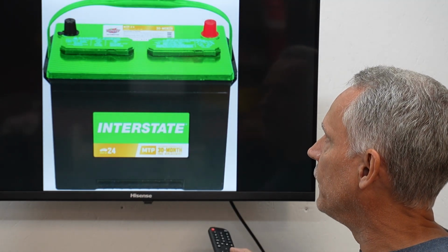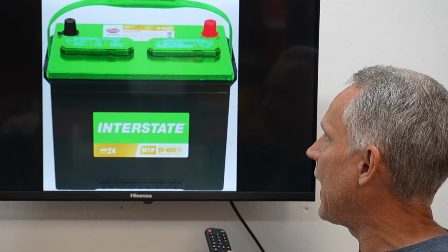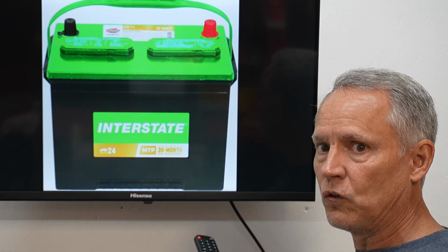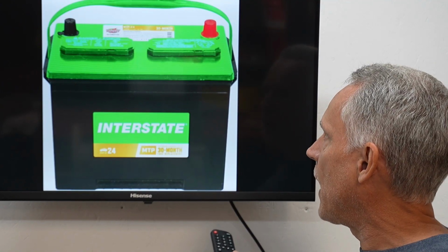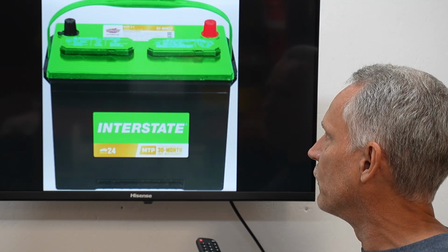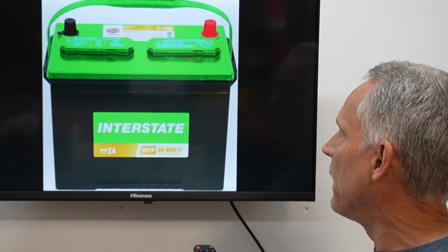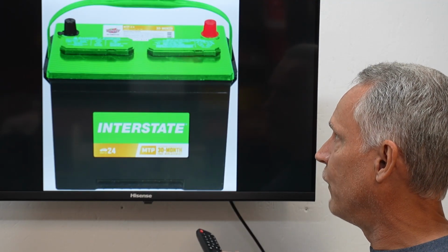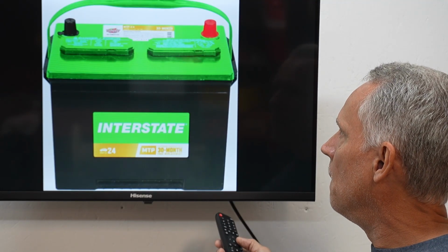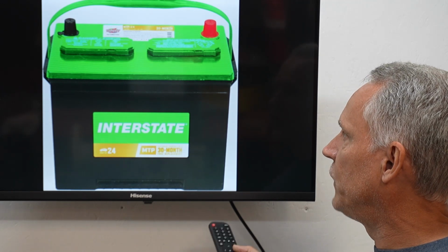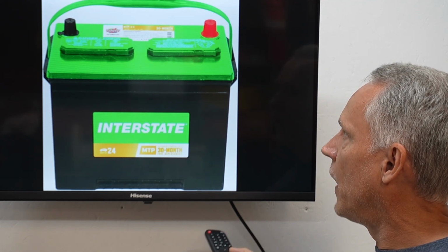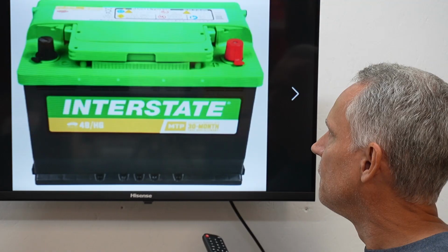Also, a different type of vent system. These caps or vents are exposed. You pop these caps off and you'll be able to see the six ports I'm talking about, three per side, to access the electrolyte down inside the battery. Also, like I said, flooded lead acid, not maintenance free. Standard, norm type FLA battery.